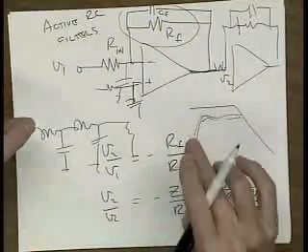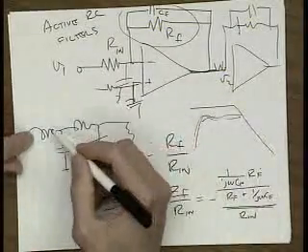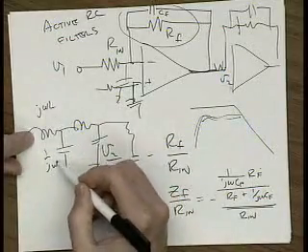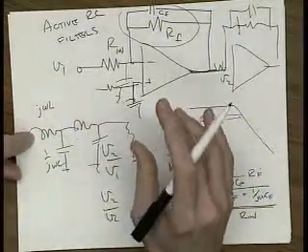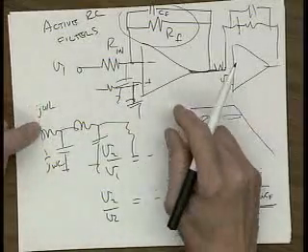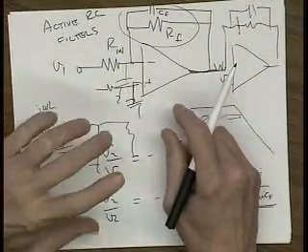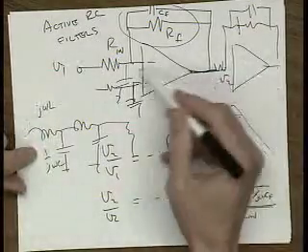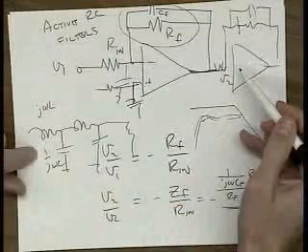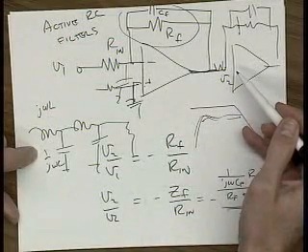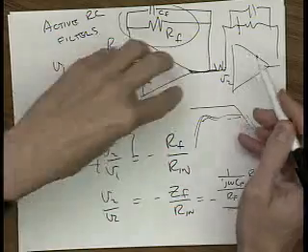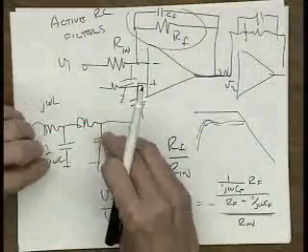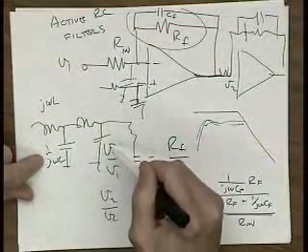But in actual fact, much of our filter design that we do, I told you we can place these poles and zeros in arbitrary places. There's lots of different structures to do it. Turns out some of the best structures are actually ones where we do effectively a simulation of LC networks, okay? So basically we can take op amps like this. If you look back in literature, there's a period of time when people did analog computers, and what they did was they used op amps, effectively things like this, and sort of modeled the differential equations associated with LC networks.